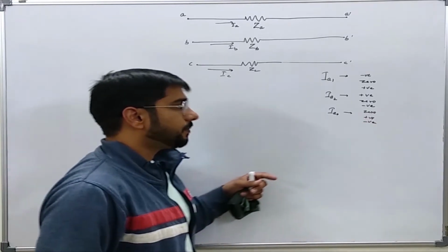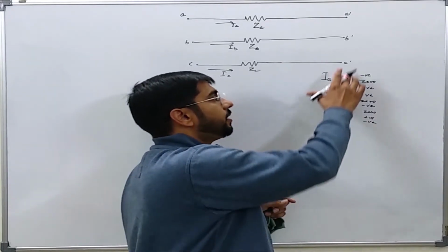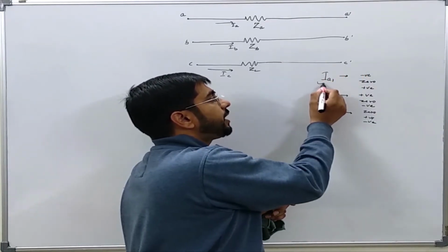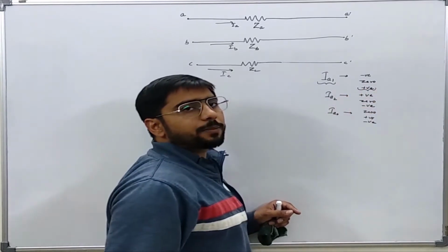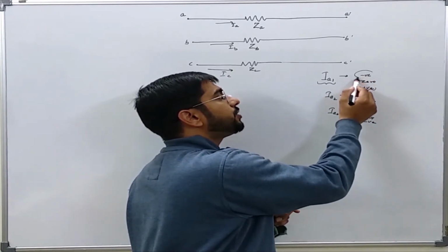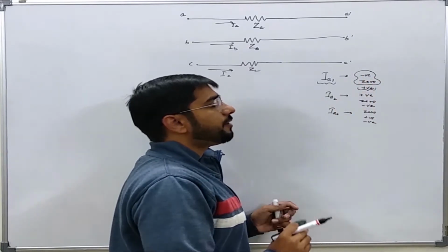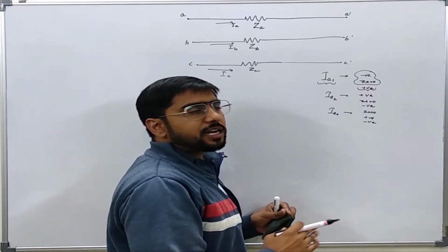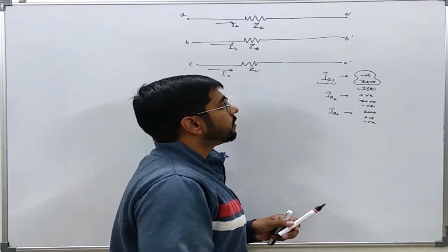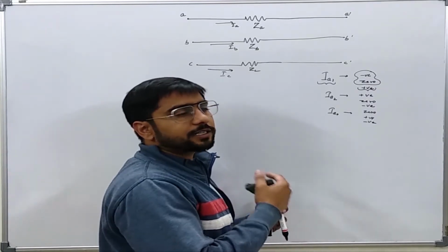So you see, unlike the case of a balanced system in which a positive sequence current creates only a positive sequence voltage drop, in an unbalanced system it will also create a negative sequence as well as zero sequence voltage drop. So in this way we cannot show the various sequence networks independently. So let us see how to proceed further in such a case.